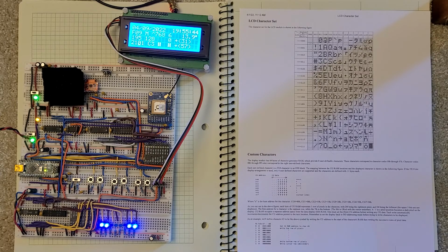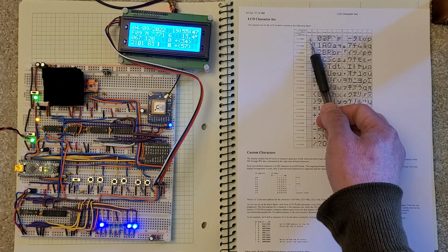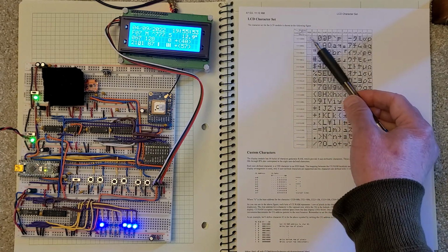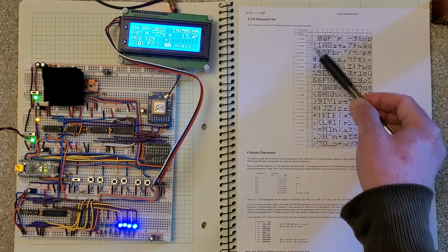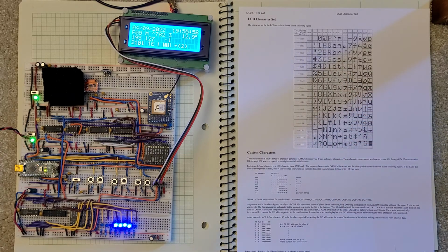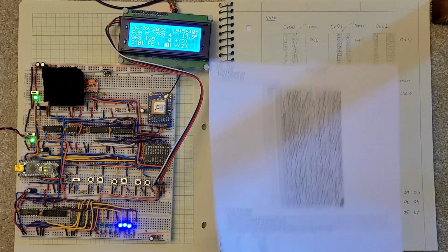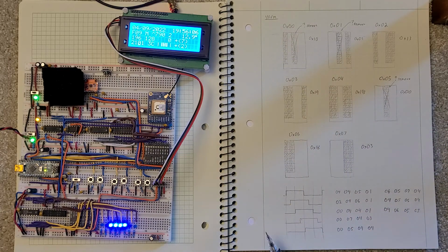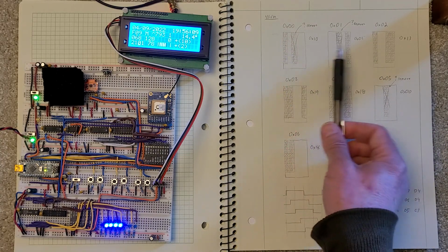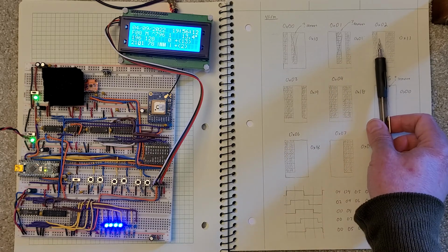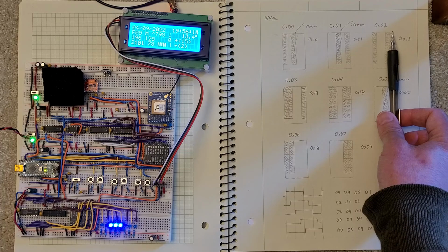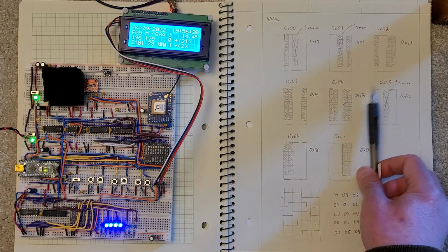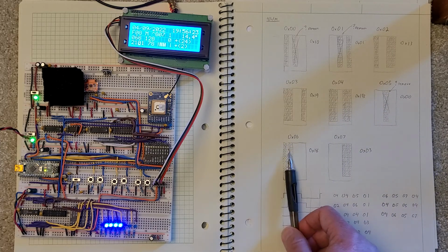And so to make your own characters, you just have to assign a bitmap, and then you can load that into one of these character positions. And then when you want to display it, you just tell the display to write whatever value is stored in that display position. So what I did is I made a set of bitmaps for each of the characters. And so, this is the left margin, right margin, left margin with an off and an on LED, right margin with an on and an off, 2 on LEDs, a blank, and then a left and a right LED on.